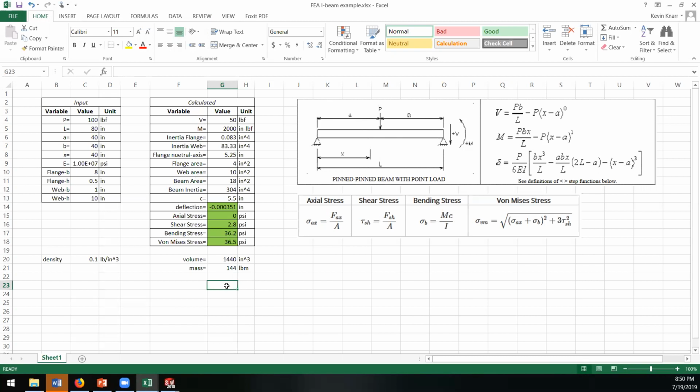We use FEMAP, and FEMAP's just the FEA software that does the geometry and stuff, and then Nastran runs the analysis, right? Same with NX, actually. Nastran is the solver. I don't know what solver SolidWorks is using, but all this stuff you see when you're drawing meshes and all that is just to make an algebraic matrix that they give to a solver, and the solver is cranking that out and only giving you numbers. Then SolidWorks is interpreting those numbers into colors and shapes and deflections, right?